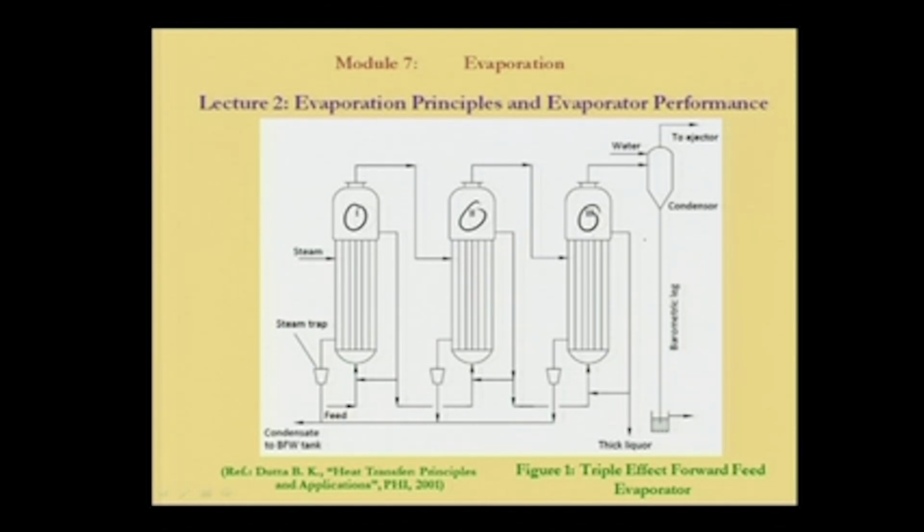The advantage here is that the steam we are putting in only once, but it is used in multiple evaporators. So this vapor which is coming out, its energy is used again for evaporation. Therefore, the economy gets increased.